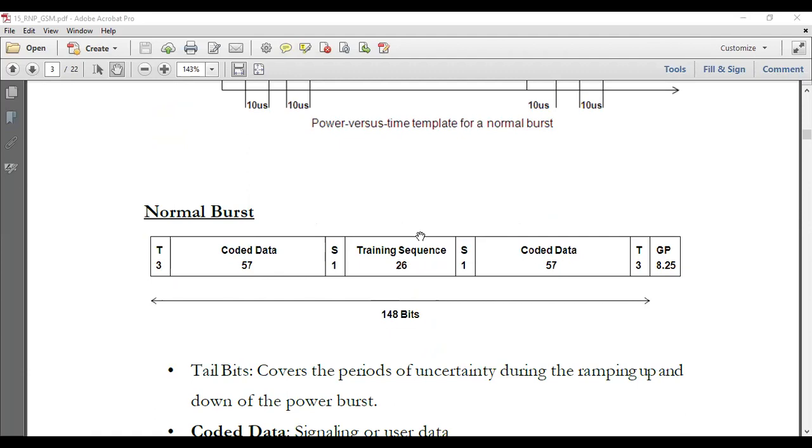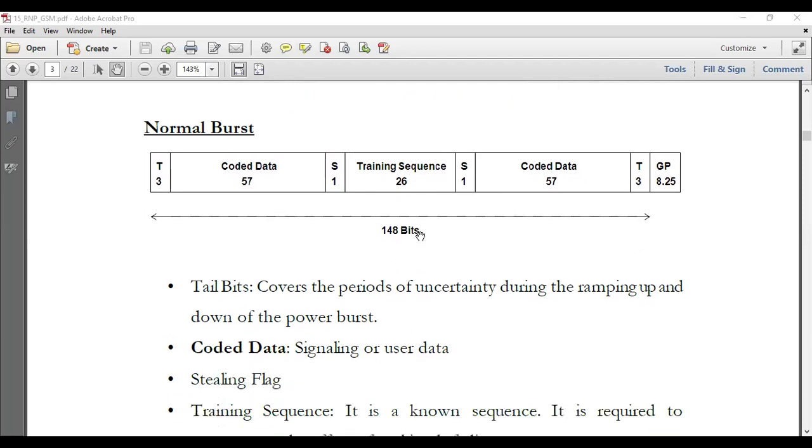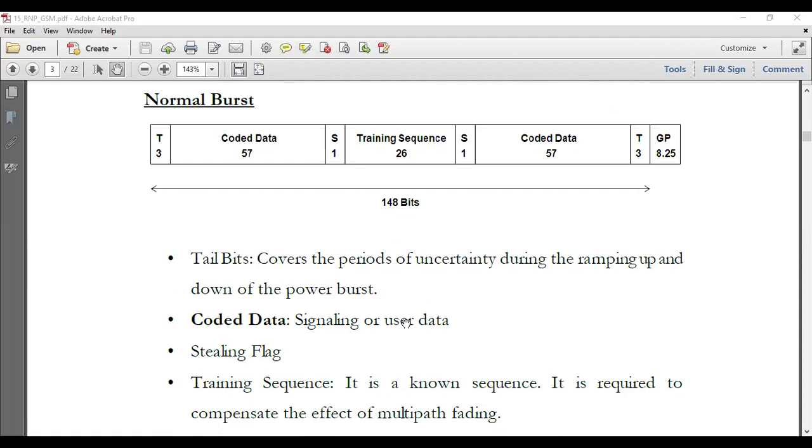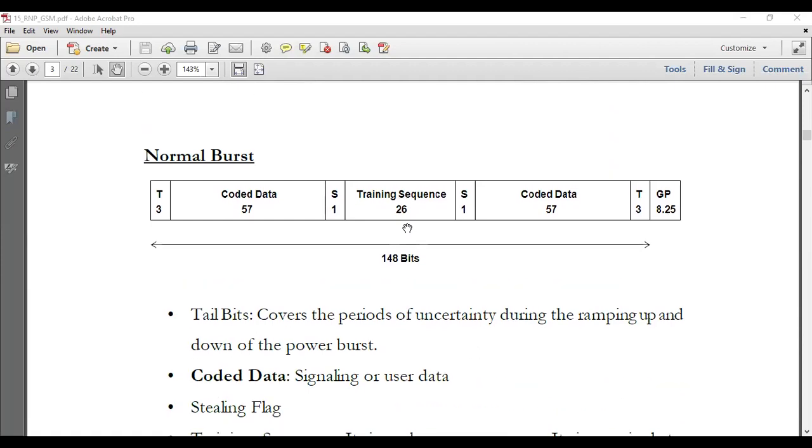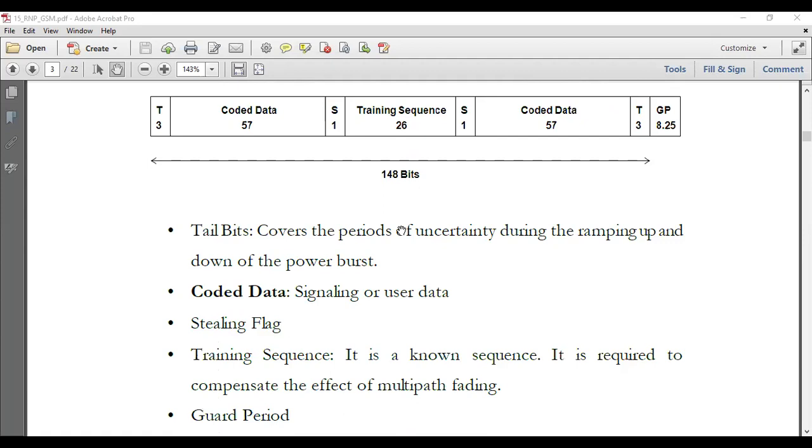We said that you can set an equalizer at the receiving end to reshape the filter, and you actually can get rid of some errors. So a frequency selective fading environment can be better addressed this way.